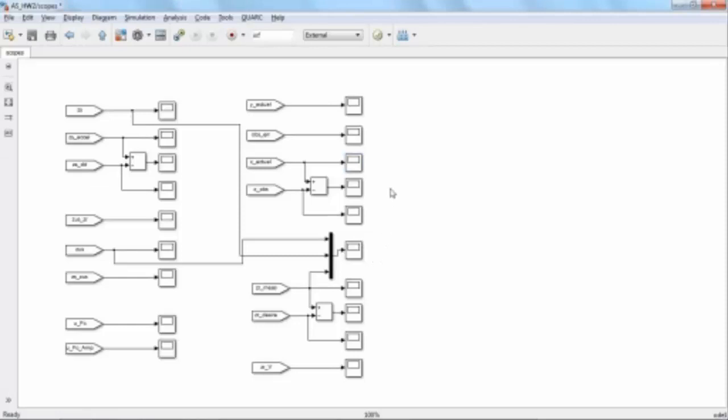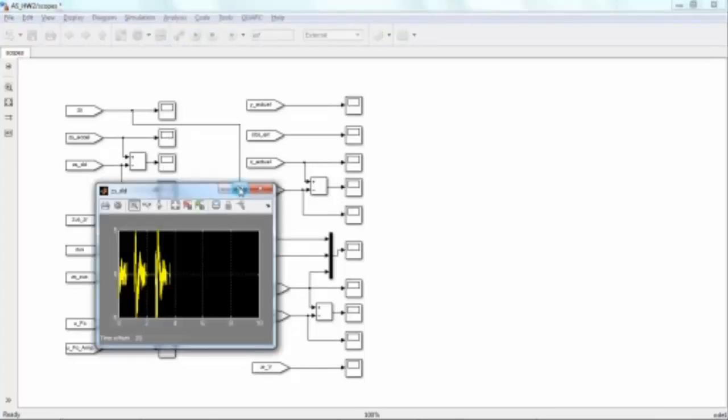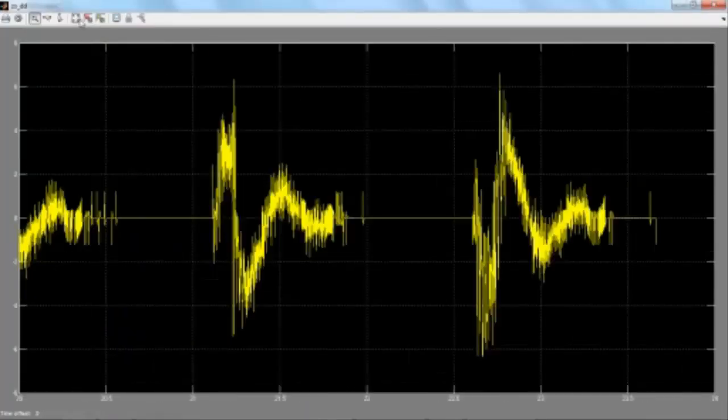For our system model in particular, we also need a second derivative to actually get our output. And that is quite an issue. If we have to do a second derivative, then we end up with quite a noisy signal. So this is the output of our second derivative filter to get the acceleration of our car model.